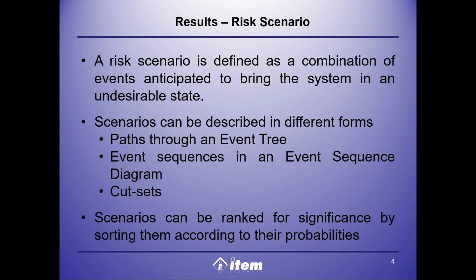For instance, if you are performing an inductive, bottom-up analysis, a scenario might be represented as a specific path through an event tree or as a chain of events within an event sequence diagram. However, because we are utilizing deductive fault tree analysis for our reactor vessel, our scenarios are represented as cut sets, which are the specific combinations of basic events required to trigger our top-level explosion hazard.